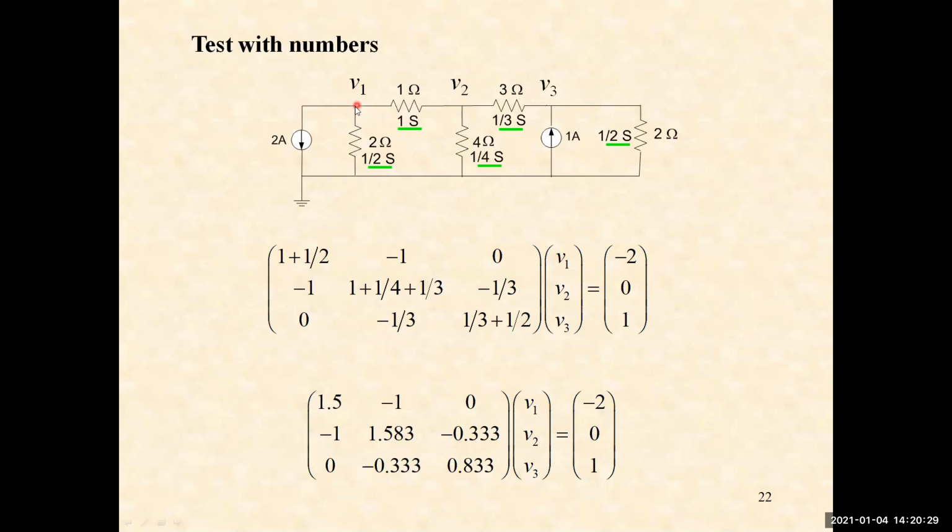So first, what is the resistance here? 2 ohms, no? 2 ohms is nothing but 1/2 Siemens, that is called mho. G is nothing but 1/R, so 1/2. Here also G is nothing but 1/1, so 1 Siemens. Convert all resistances into mhos or Siemens. It's clear. And then this node is connected between these two, that's why 1/2 plus 1, 1 plus 1/2 like this.